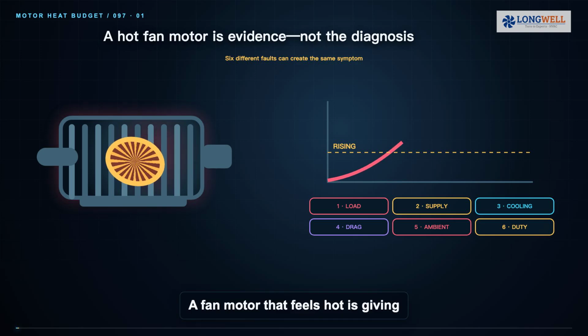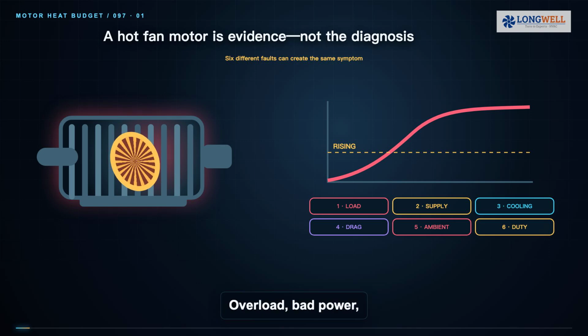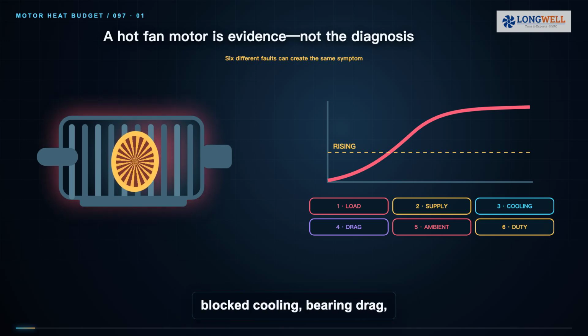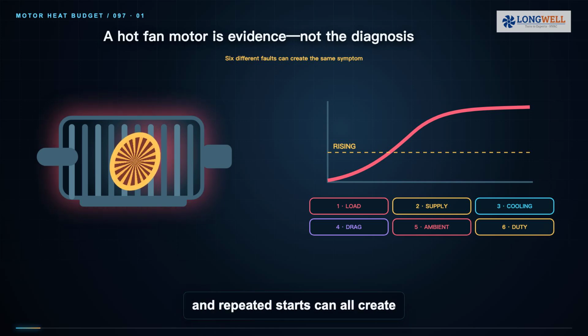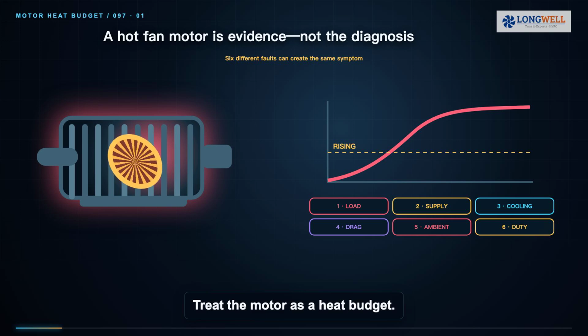A fan motor that feels hot is giving you evidence, but not a diagnosis. Overload, bad power, blocked cooling, bearing drag, high ambient temperature, and repeated starts can all create the same symptom. Here is a fast way to separate them.